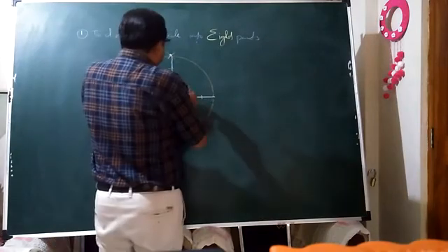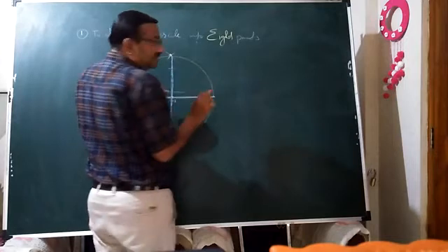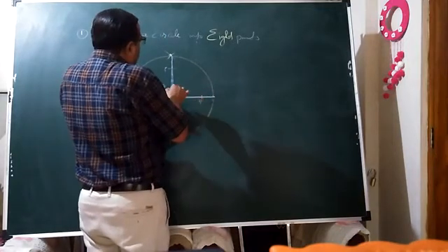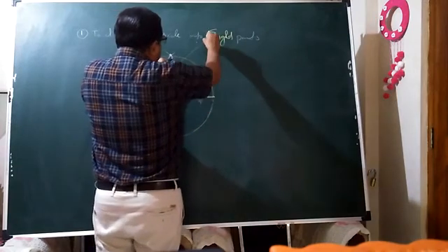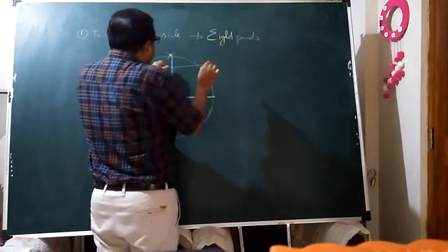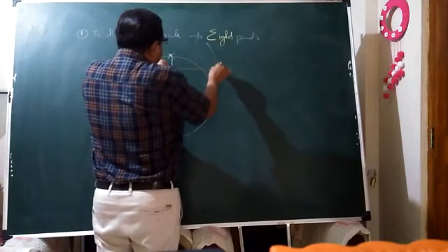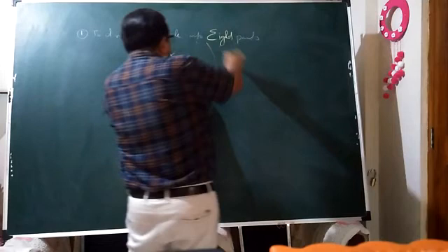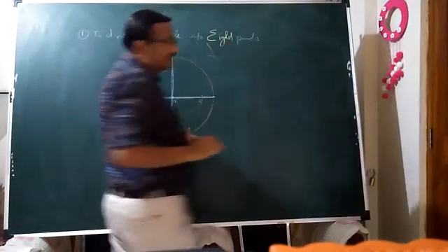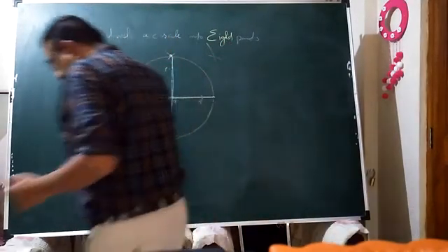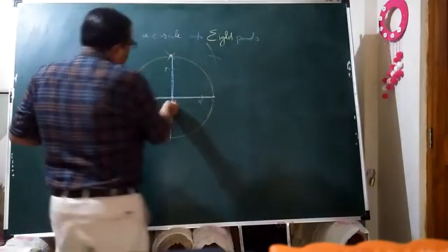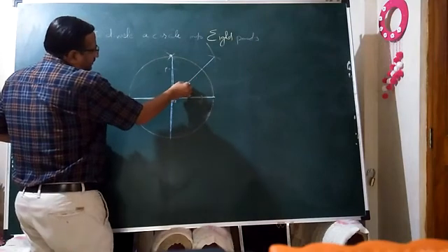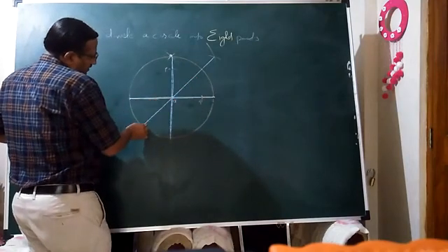After that, you can change the distance and by interchanging the position of the needle, from P and from Q, we are going to get intersecting arcs in this way in the space. First arc of any radius from P. Now the next position of the needle will be over Q and with the same radius get an intersecting arc in this way. Now this point of intersection of both these arcs, you have to make it pass through the center of the circle O and extend it.